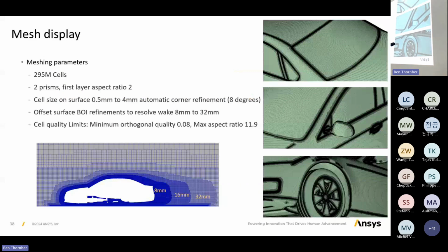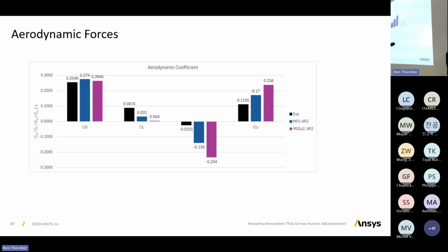And then we're working on transferring some of the findings from the SBES run, because the SBES run used an angular refinement criterion. So we use an angular refinement criterion now for the LES runs as well. It does use more refinement compared to the SBES, because we don't have prism layers in that case. And this is the sort of mesh that we are then using and evaluating. It's a bit coarser overall, 4 millimeters on the body, but the refinement toward the curvature regions is a lot better, and so the results did improve. This mesh also has the grooves on the tires, by the way.